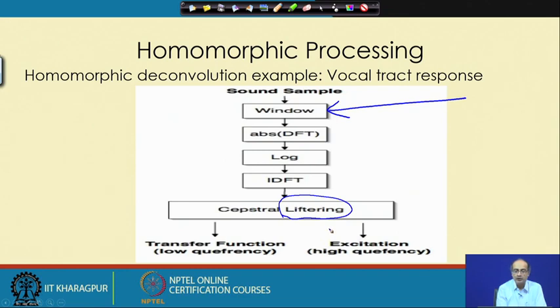The reason is that the original signal was real. So, the complex Cepstrum also would be real, and because it is real, we do not bother about the phase or the phase unwrapping, okay. We are not interested in that.